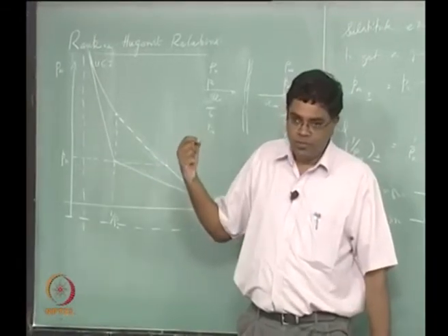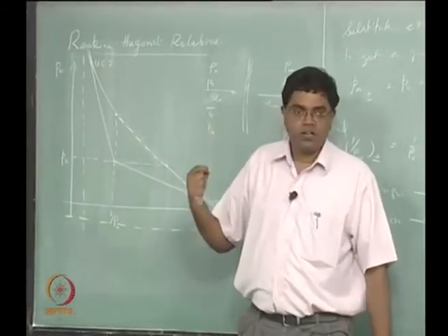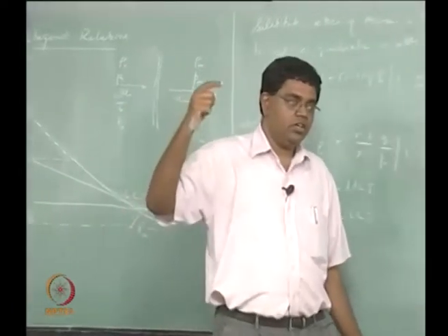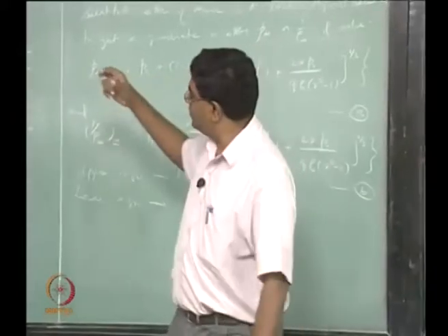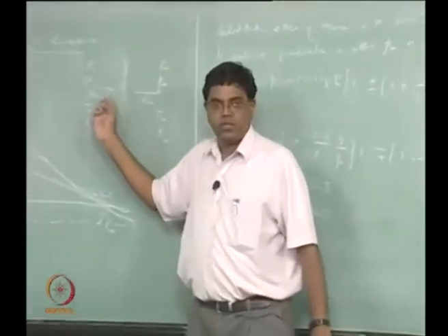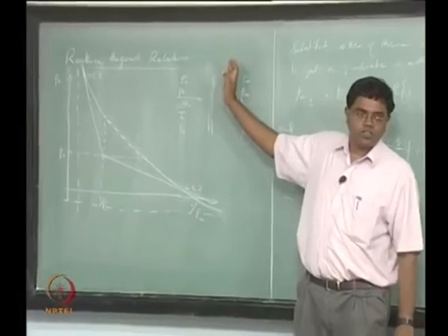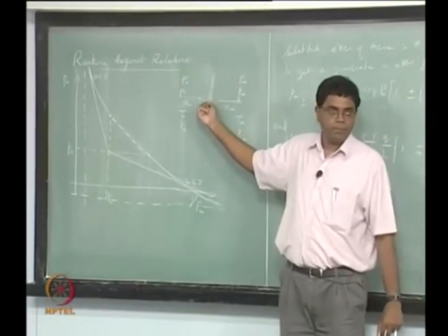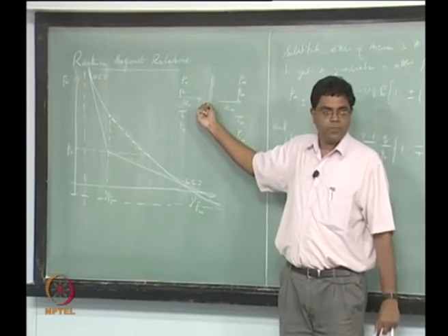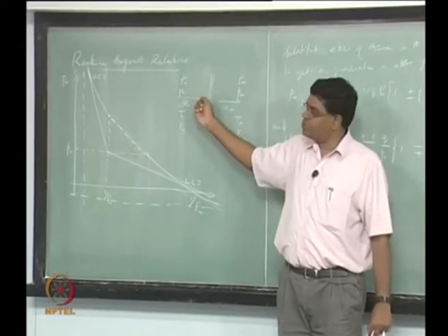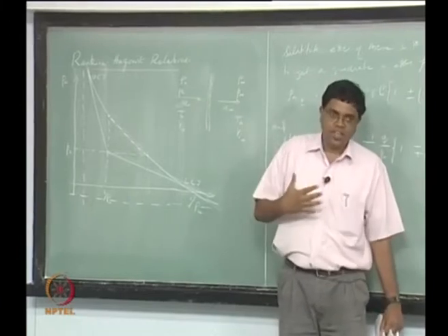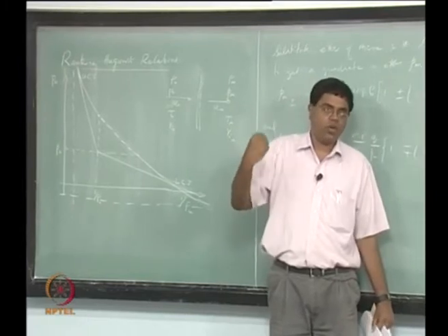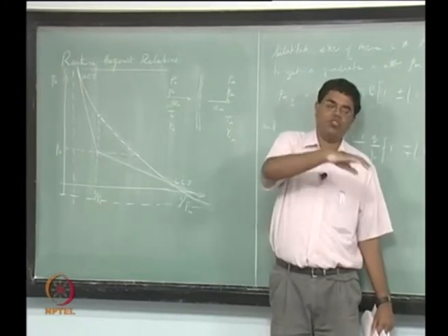Now keep in mind, how fast the wave is going to travel is information that's contained in U naught, okay, because in a wave fixed coordinate system you are going to have the reactants travel to the wave at that speed, and that information is now in our scheme of things embedded in m dot, because m dot is the one that's containing rho naught U naught as well as rho infinity U infinity.